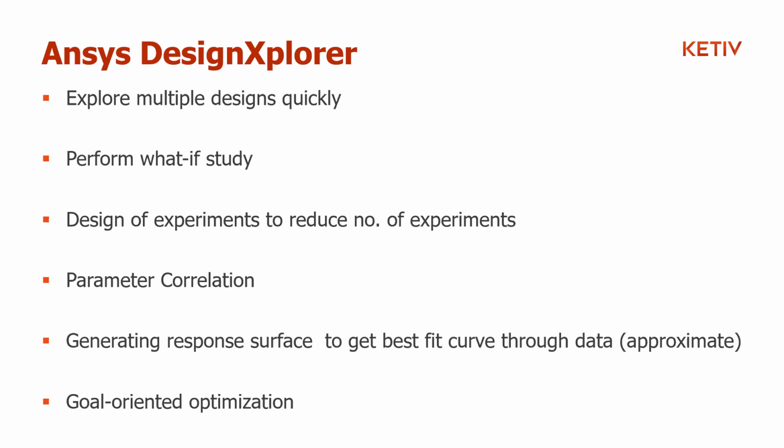One, obviously starting from the basics, you can explore multiple designs quickly. You can do a parametric study wherein changing your input parameters will help you quickly assess what kind of impact you'll have on your output. You could also do design of experiments to actually reduce the number of experiments you'll have to physically perform to establish a relation between your input and output. So there's always the cost saving aspect in doing something of this sort.